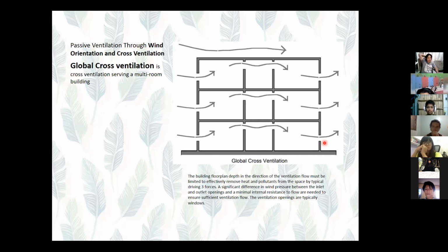It was in a townhouse before, when I was in Manila. Which subdivision is that? You can't put openings on all sides because the firewall is at the limit. If that's the case, since it's a two-story, you can put mechanical ventilation and then one exit at the top, a window. It's like a clerestory window.